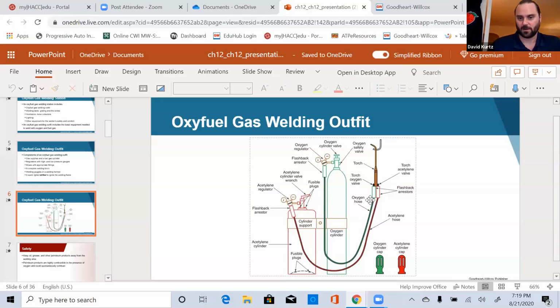After them, we connect those to our hoses. Hose on the left, oxygen; hose on the right is acetylene. If you take a look, everything is color coded with green and red. Oxygen is mainly going to be green and red. Acetylene is going to be all red for the hoses. The regulators are going to be red. You might see the cylinder either be red or black.